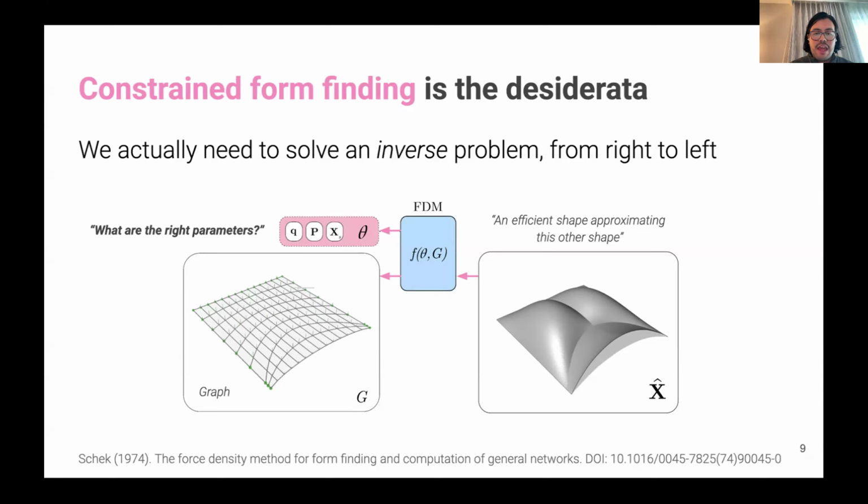So just quickly, we iterate with this optimization. We iteratively change the parameters until some convergence where we have some solution. And this happens over a number of steps. And if you compare gradient descent with something like evolutionary algorithms, this is one of the key selling points. You'll get a solution in only a couple of seconds, which would be 43.7 times faster than if you were to do this with something like Galapagos in Grasshopper. So faster solutions for you to do more design exploration while satisfying design constraints.